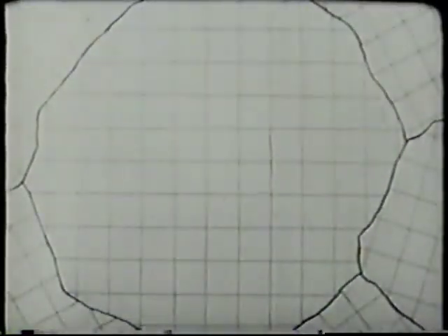In growing, adjacent grains make contact, interfering with the free growth of the outermost cells. These cells, sheared and broken during growth, give the grain its jagged and irregular shape, although the body of the grain is regular and crystalline. It is the grains and their boundaries that constitute the network structure shown in the photomicrograph of an aluminum alloy specimen.